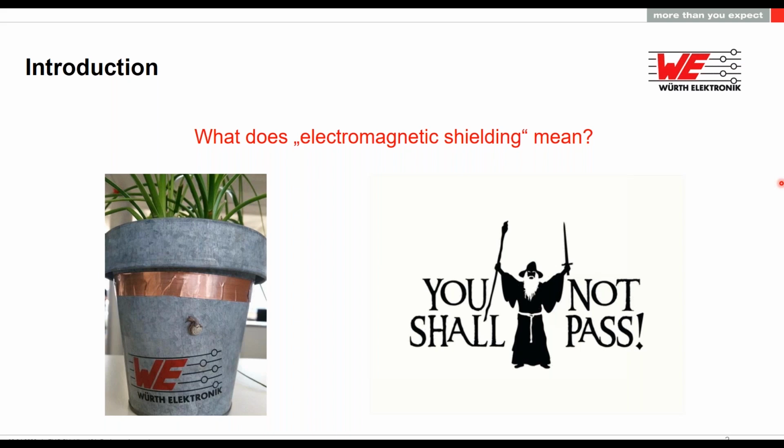For example, RF stages are very sensitive, so it's really common to protect them with shielding in order to avoid problems coming from coupling or interference with the power stages of the design. So as we said, mainly it is to place a shield between undesired noise and our device or parts of our device.